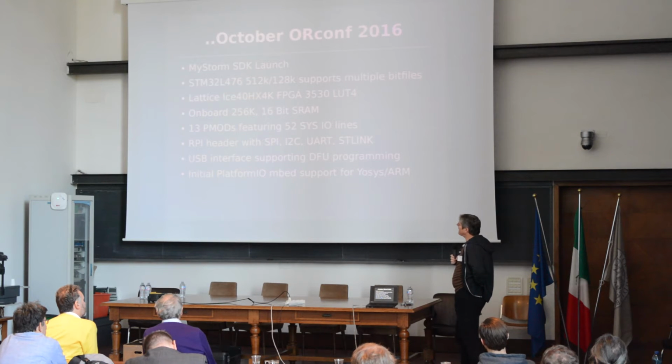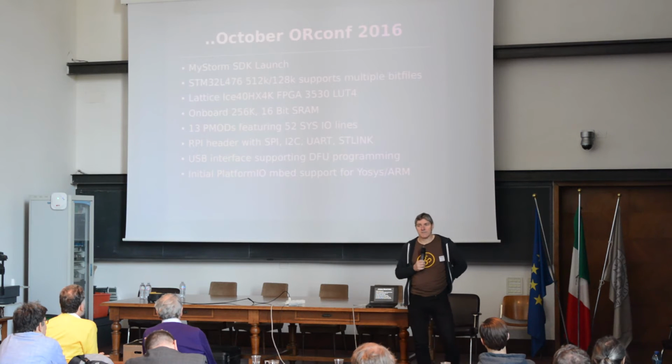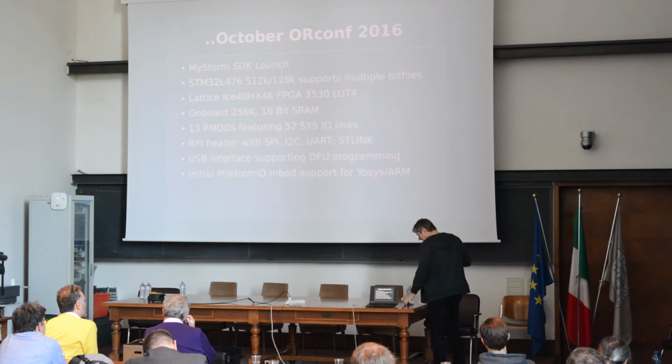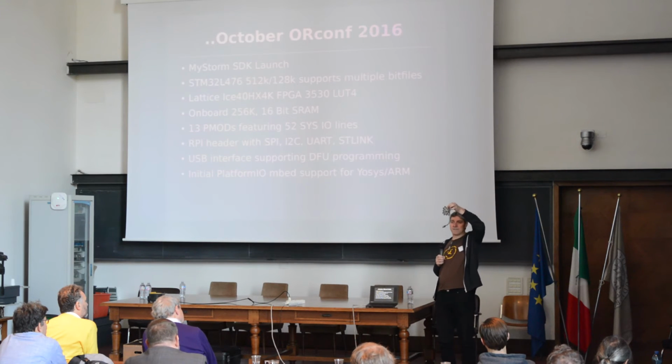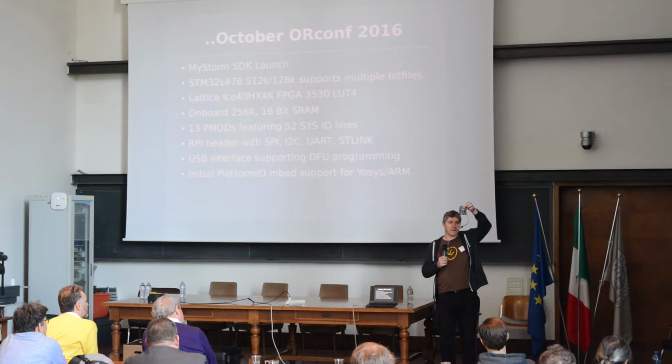On board, we added a 256K 16-bit SRAM, and that actually sits on the rear of the board. I have a board here, actually. You can see the size we're talking about. I've actually got an ST-Link 2 programmer hanging off it for the ARM32 because I prefer to use that for my development processes. So as you can see, this board is 75 by 75 millimeters.